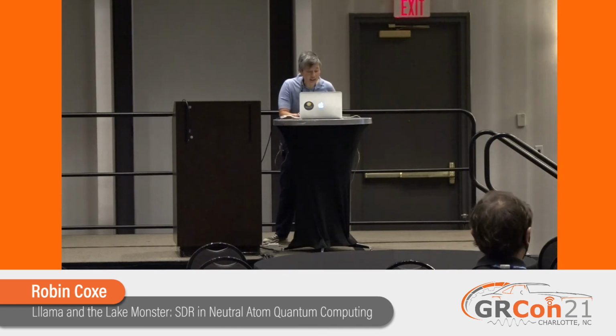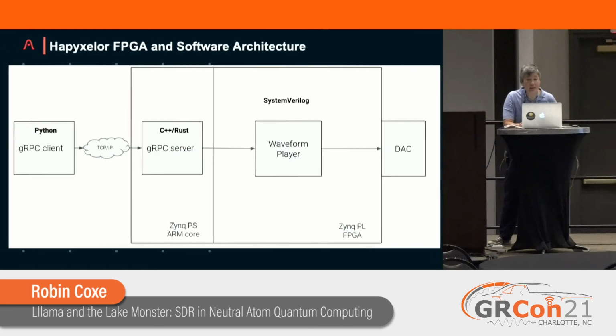Yeah, so for the DACs without the external mixer, let me just find the slide. Those are driving the AODs, and one of the things I failed to mention is the AOD tones that we're outputting are in the range about 80 to about 400 megahertz, so you can directly generate them out of the RFSoC, whereas the EOMs in the modes that we are operating in to transition between the two states of the 1 qubit gate require 9 to 11 gigahertz tones. So we need to upconvert because the RFSoC's maximum output frequency is about 6 gigahertz. Makes sense. Thanks.